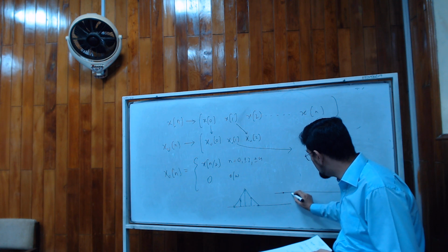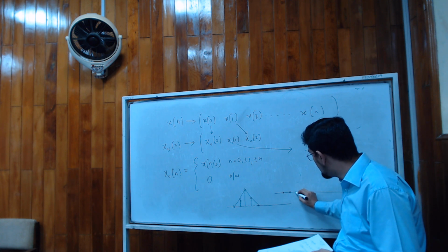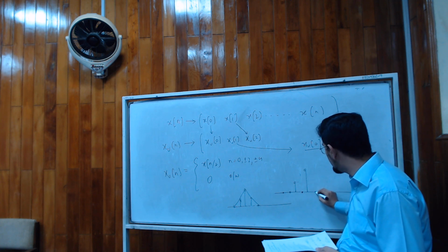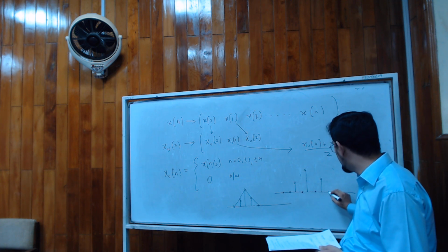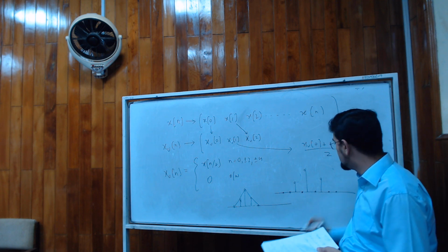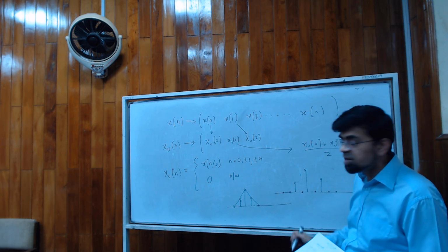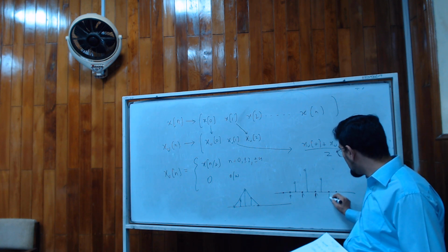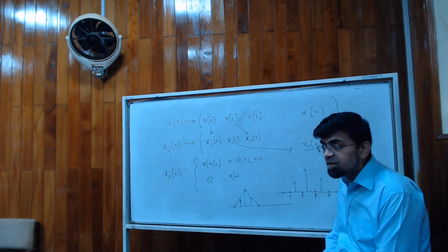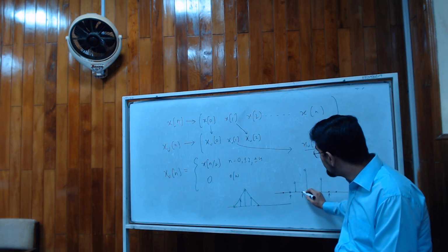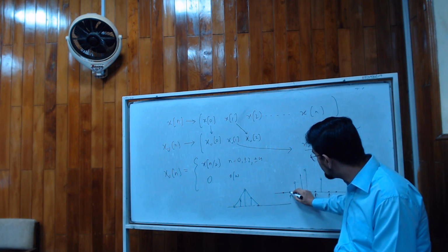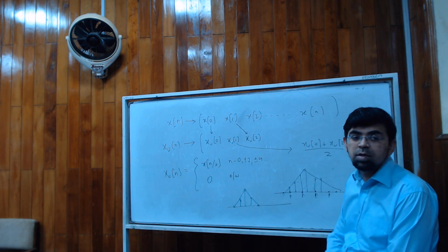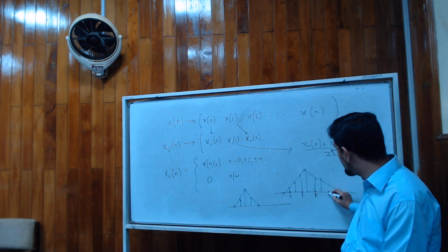So this is at 0, you put a 0 here, one value here, a 0 here, another value here, another 0 and so on. These are the new zeros you have placed in. These are your zero paddings. Next, you replace these by the average between the neighbours, and you get the upsampled version.